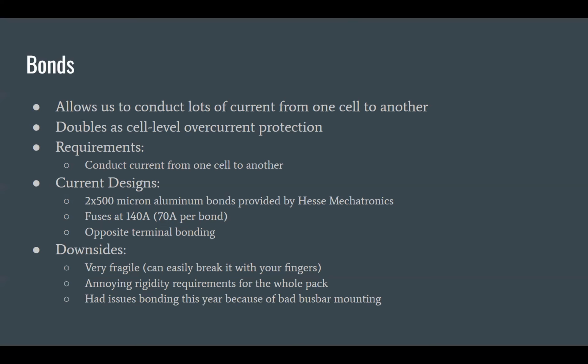And since they can total up to 560, the rule says that when we combine all of these together, this all has to go through a fuse that is equal to this, so 560 divided by 3 or less. If you do this math out, this is 180. So the final fuse has to be 180 amps or less.